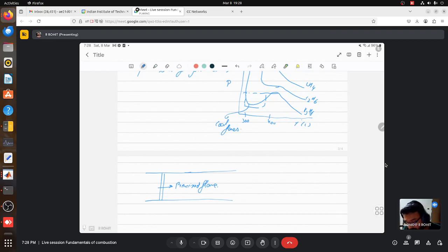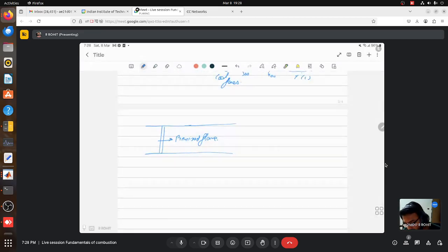This initial flame can be ignited using piloted ignition, which depends on the magnitude of energy of the source used and the volume of the reactant mixture available. A minimum ignition energy and a critical volume of the reactant mixture are required for ignition. These quantities depend on your initial temperature and the composition of your reactant mixture, and we'll see how composition affects this subsequently.